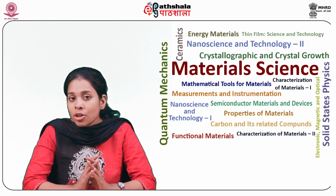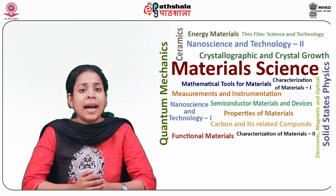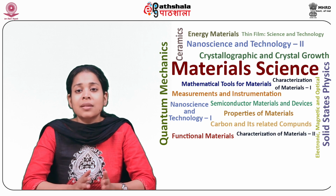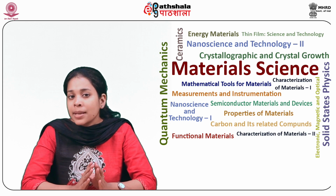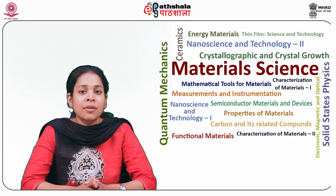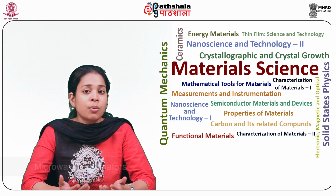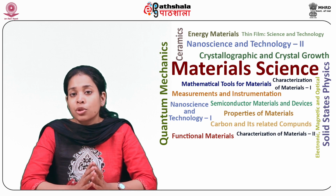Since the operation of a microwave resonator is very similar to that of lumped element circuit resonators of circuit theory, we will begin by reviewing the basic characteristics of series and parallel RLC resonator circuits. For communication through a microwave resonator, the waveguide plays a very crucial role.